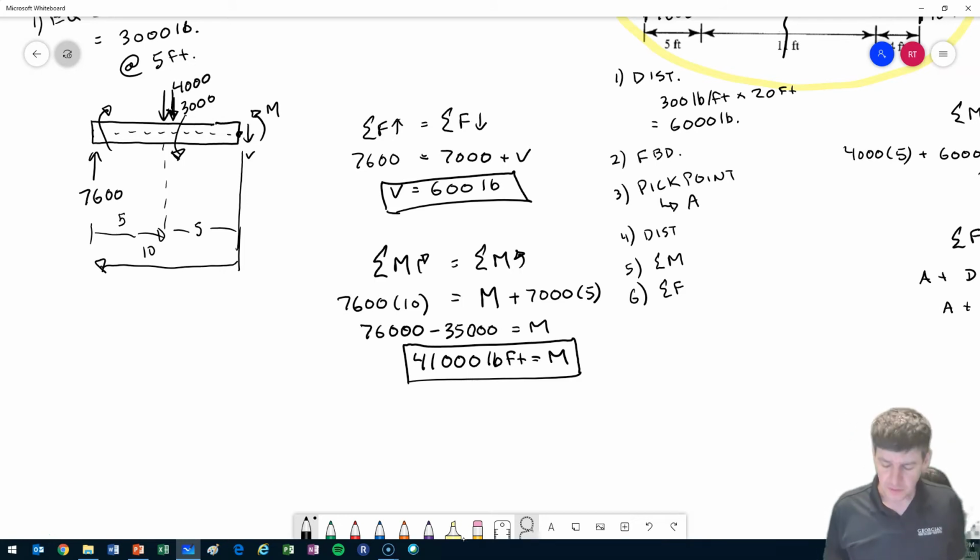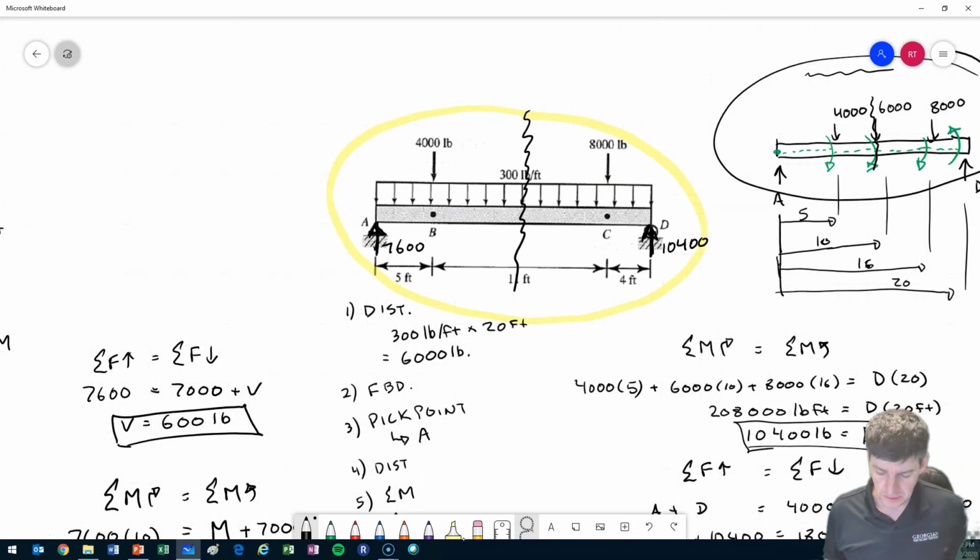Okay, so really the careful thing that you have to take is if you have a distributed load that is in the middle of the object or where you're slicing, don't just keep going from the external load work you were doing. You've got to backtrack right to your starting point. There's definitely some questions like this that come up in your TSSA exams, so just make sure you're careful with this stuff. If you have a slice right through it, you got to backtrack if you're going to find the right answer at the end.